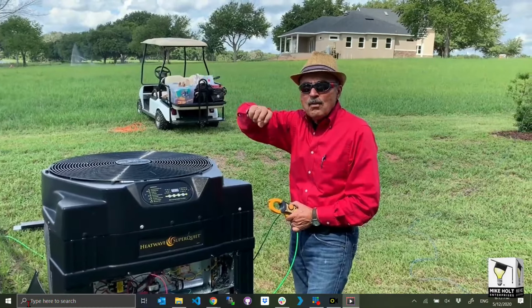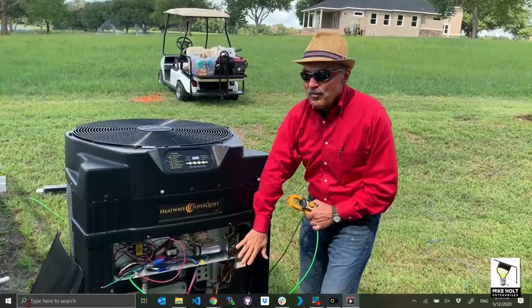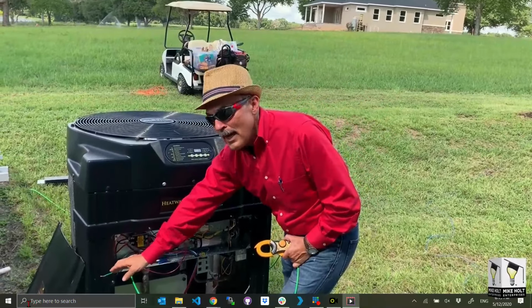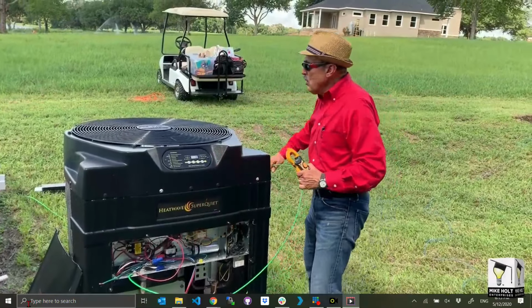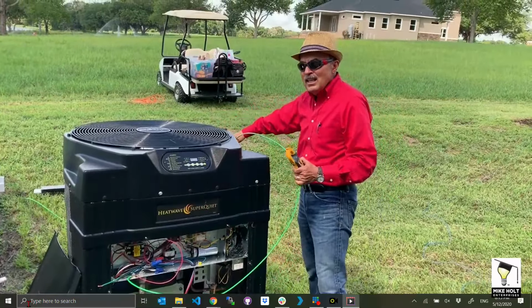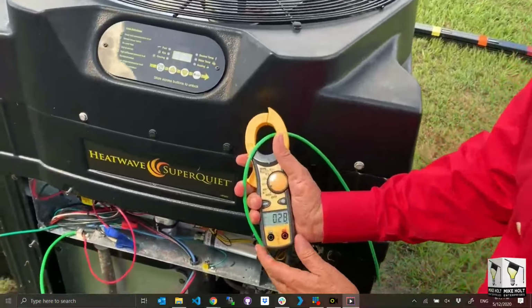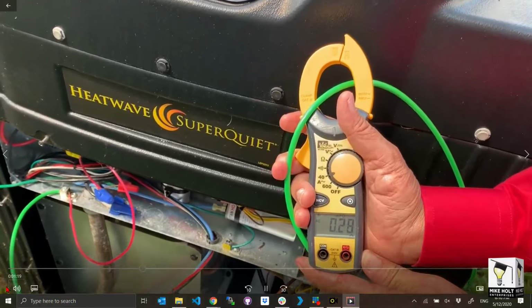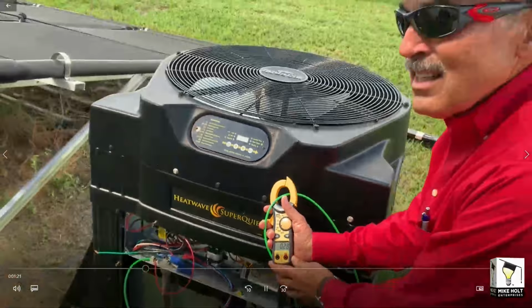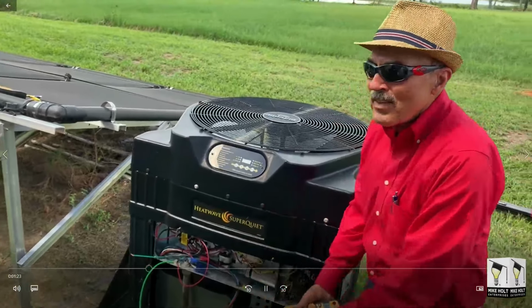So now let's see what happens. If you have something that's metal without an effective ground fault current path, and you run a wire over to a ground rod, okay, Dave, you turn it on? It's on. Okay, and we turn it on, we'll find out how many amps it's going to take. That's a 50 amp breaker. Carl, how many amps is that drawing? 0.28. 0.28. Think about this, Carl.